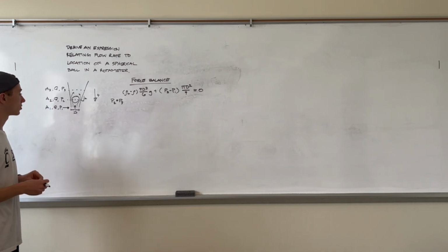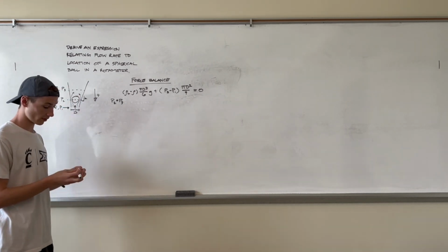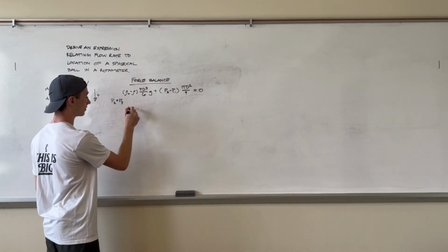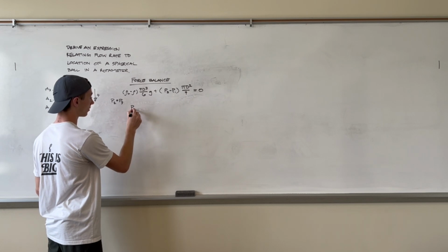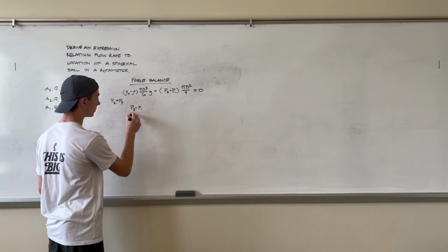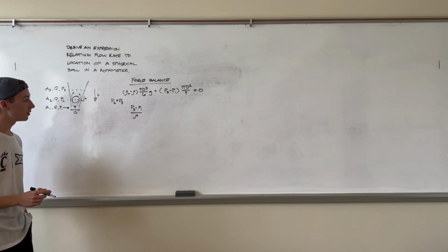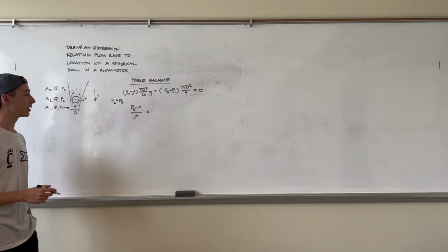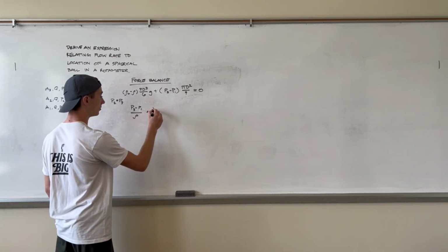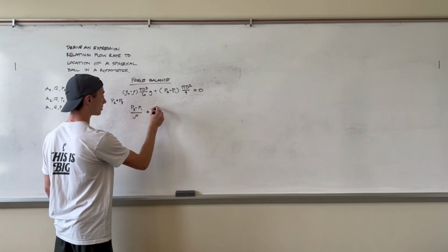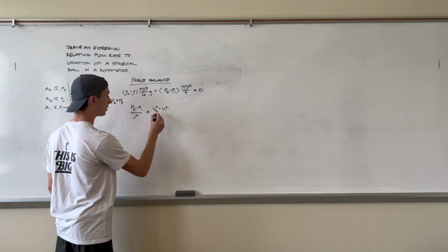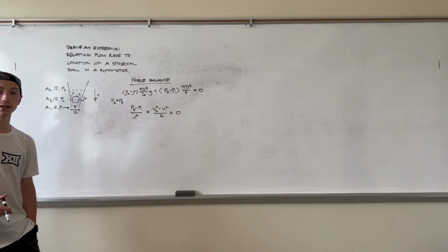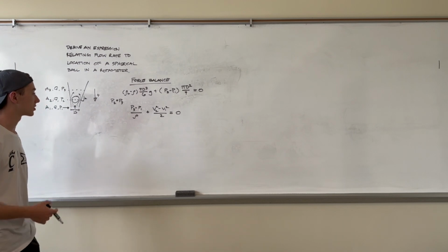You remember from Bernoulli's equation, the change in pressure, meaning P3 minus P1 over rho, plus the change in the square of the velocities over 2, so V2 squared minus V1 squared over 2, is equal to 0. We are ignoring any viscous effects here. That's just another assumption we're making.